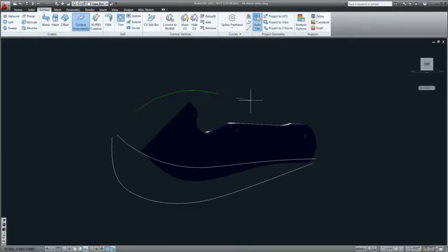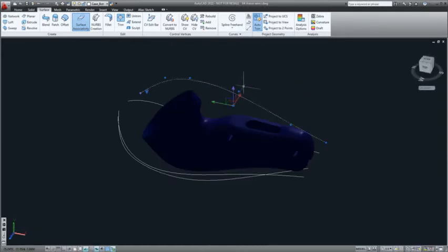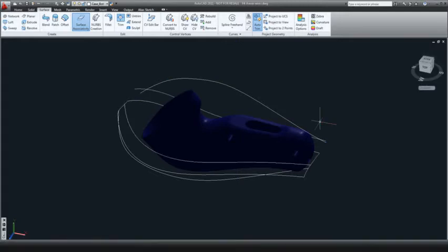Once we have the sketch, we can use that image to trace some splines in AutoCAD. We'll make some curves using the new spline capabilities, which allow you to create a spline using control vertices and also use direct manipulation to stretch, add, remove, and refine vertices without going into spline editing commands. Note that the direct in-canvas manipulation is made possible by AutoCAD's Gizmo tools. Once we have all our curves, we'll start creating surfaces.